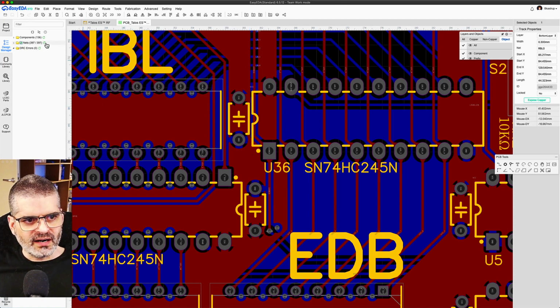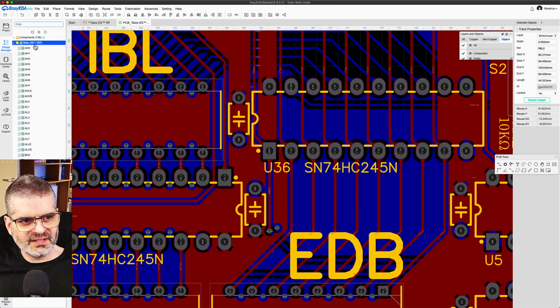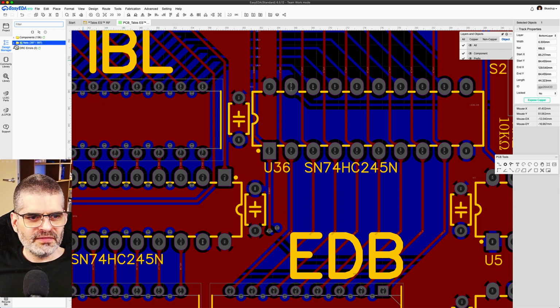And that's what you have to know, because if you do a copper fill and then you ask the tool, are all my nets routed? Oh, it tells me yes, 397 nets are routed out of 397. Everything is routed. What it will not tell you is that power is going through a tiny bottleneck. So it is routed. The tool will tell you, yep, it's fine, everything's okay. And then the thing will not work.